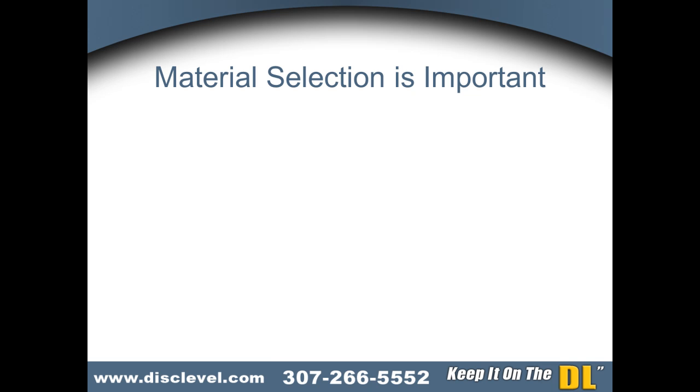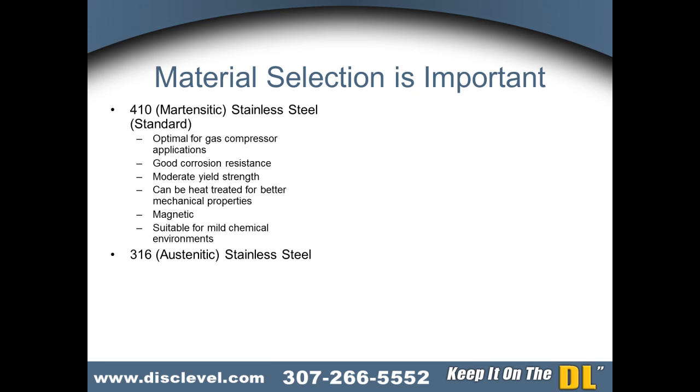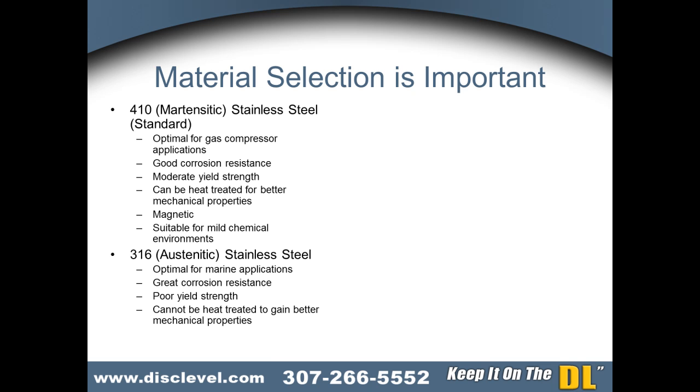Material selection is important. 410 martensitic stainless steel, the standard. Optimal for gas compressor applications, good corrosion resistance, moderate yield strength, can be heat treated for better mechanical properties, magnetic, suitable for mild chemical environments. 316 austenitic stainless steel. Optimal for marine applications, great corrosion resistance, poor yield strength, cannot be heat treated to gain better mechanical properties, non-magnetic, mostly chemical resistant.